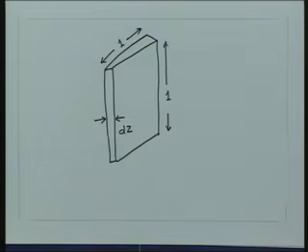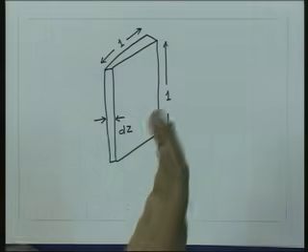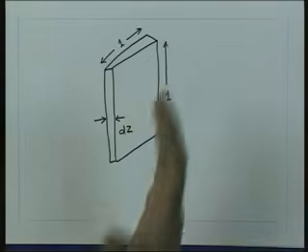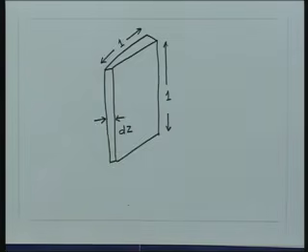On the surface of the conductor, I am asking if I take a thin layer which is parallel to the surface of the conductor, and since there is a finite conduction current density there, we can ask how much is the power loss in that thin sheet, and then if we integrate over the entire depth from the surface of the conductor, we will get the total power loss taking place in the unit area of that conductor.